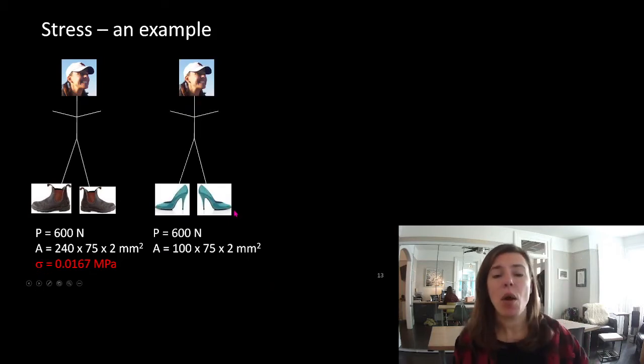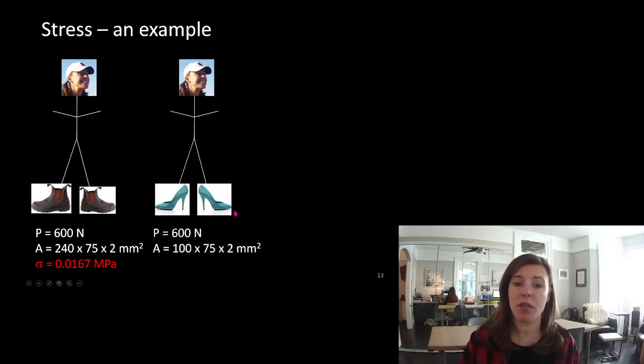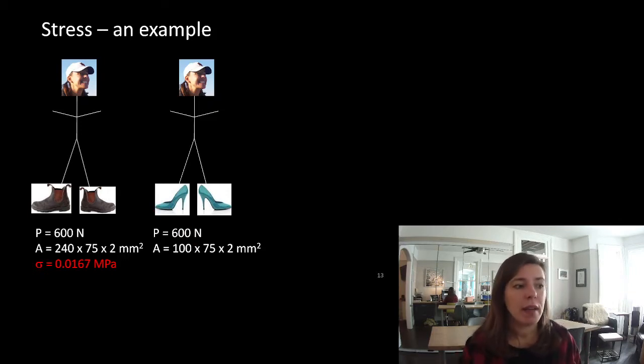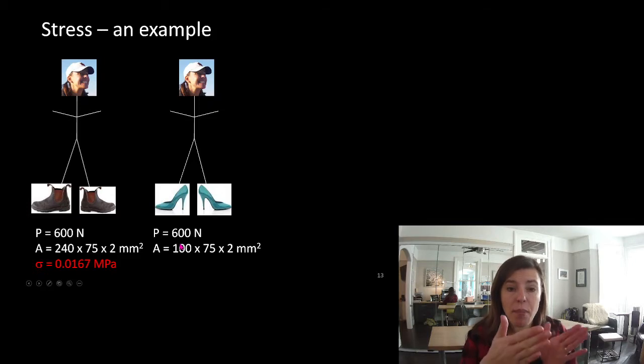What do you think? Shannon in heels, more or less stress on the ground? Well, you know that if you're walking in your heels, you punch through the ground. So let's ignore the heels for now. We'll assume I'm standing, and this is the surface area. So I've got the same amount of load. I haven't changed weight. I am still 600 newtons, but the area of my foot that's in contact with the ground has gone down. Instead of almost 10 inches long, it's only 4 inches long by 3 inches.